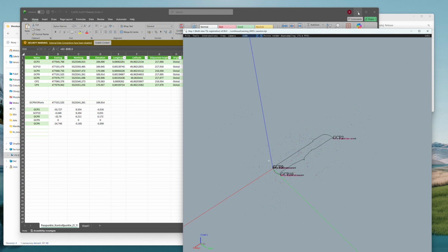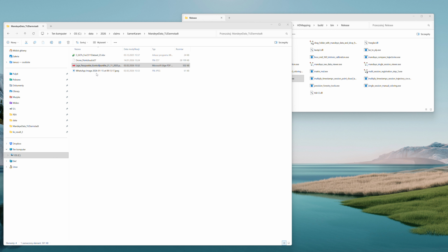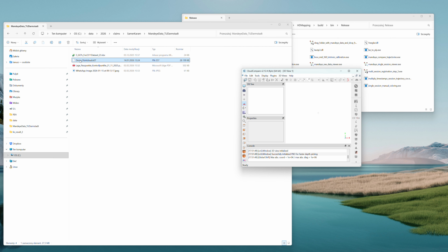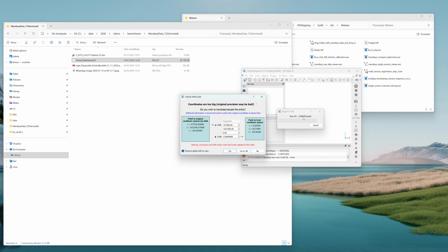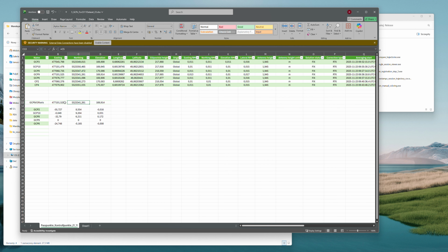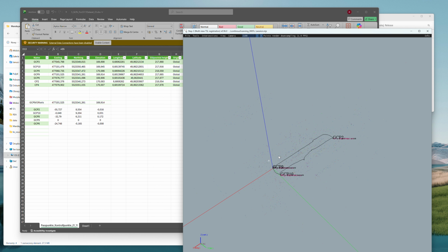this data with a point cloud from drone. So we have data from the drone. Okay, and what you have, it is in coordinate system, as you can see, that our data were shifted. Can you see this? So in that sense, we have to take this shift, and we have to apply this shift to our export. So let's go back to our export.